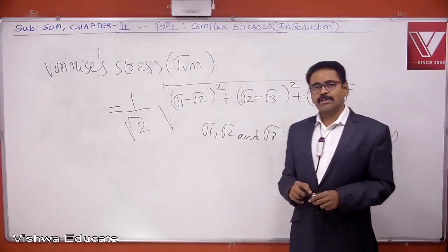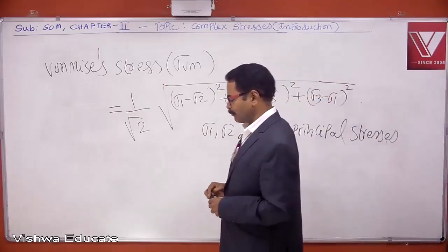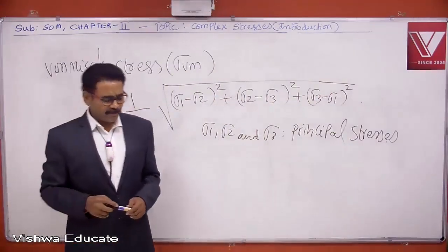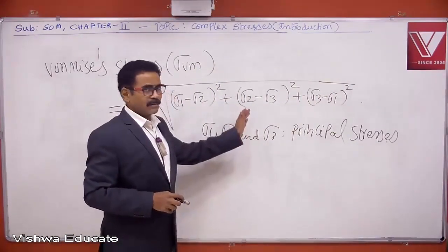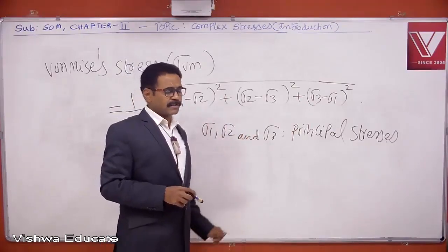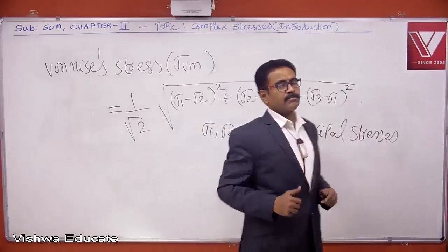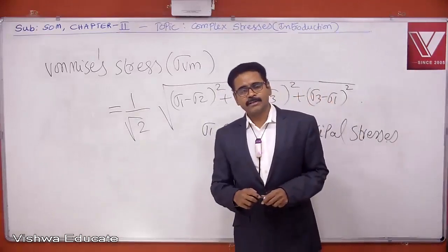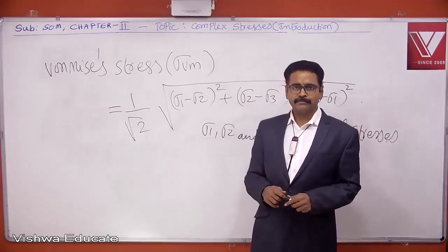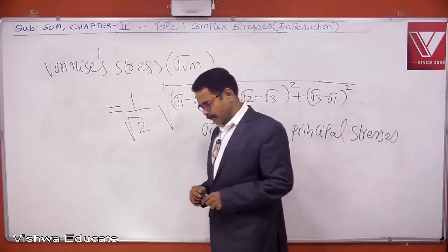Why do we need this stress? Why is it important for ductile machine elements? Practically, in the outside world, ductile machine elements are designed on the basis of Von Mises stress, not any other stress. This is the most important stress in the design of ductile machine elements. Okay, why is it important?